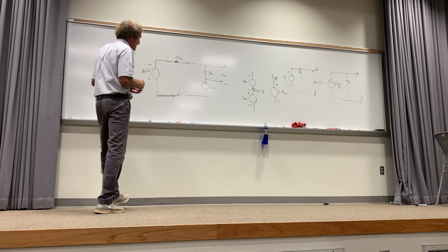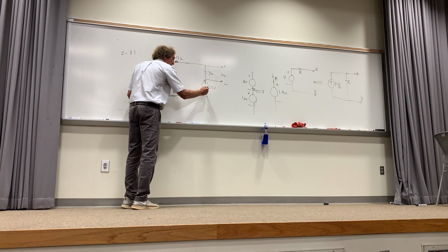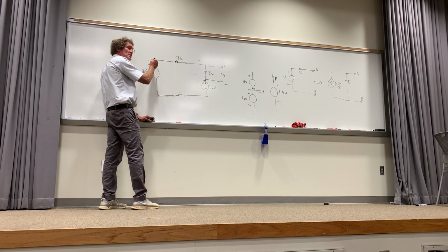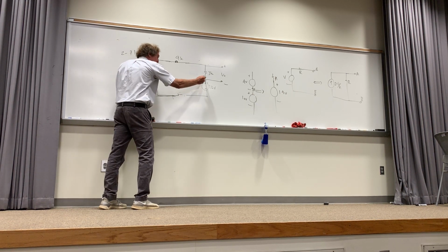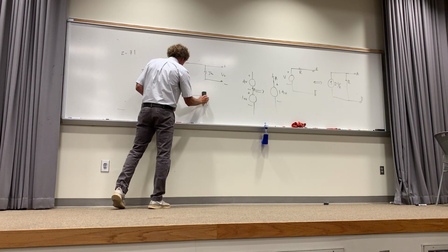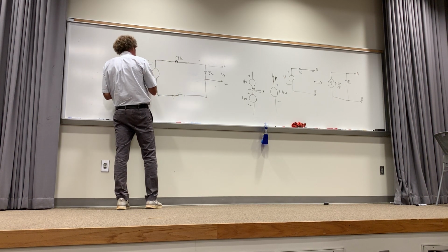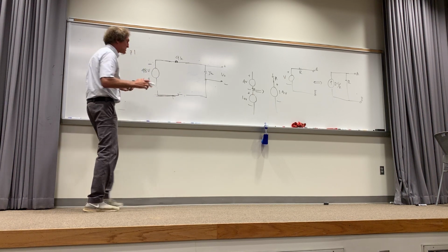Here, from this point, I have a decrease of 12 volts, right? And then a decrease of 36 volts. Do you all see that? Or really a decrease of 48 volts. Do you agree? From here to here, which means I can get rid of this 12, right? And just put 48 volts here. How many see that right there?